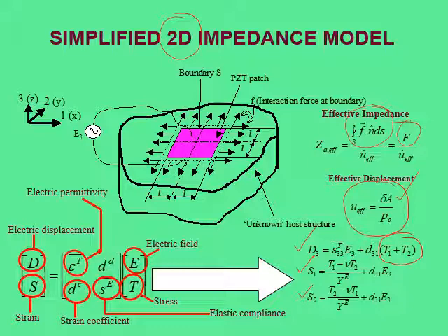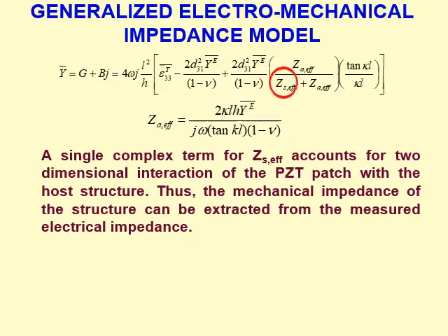That's why the two are added up, assuming that D31 and D32 are the same. Similarly, for the strain we have these terms: D31 into E3 will be there definitely, but because it's a case of the stress occurring in two directions, we have the Poisson's effect also. So making use of these equations, this simplified expression is derived.